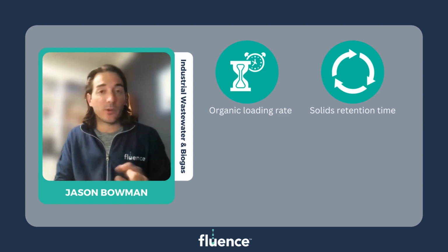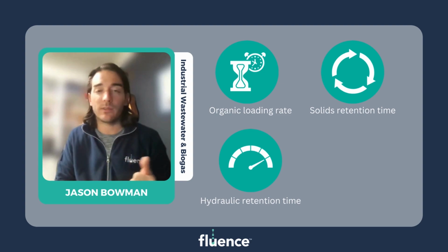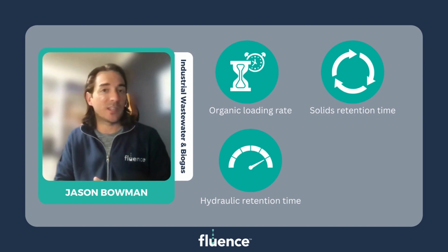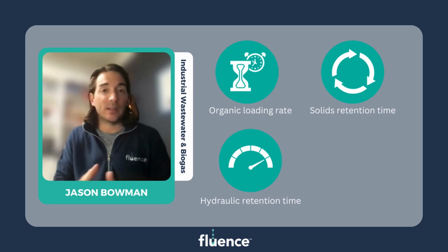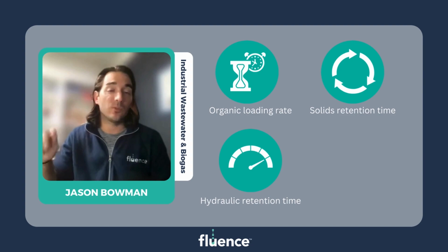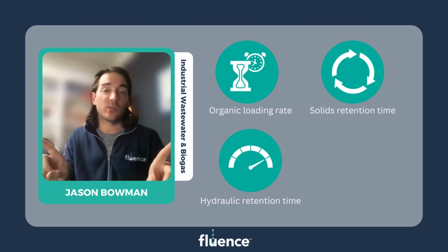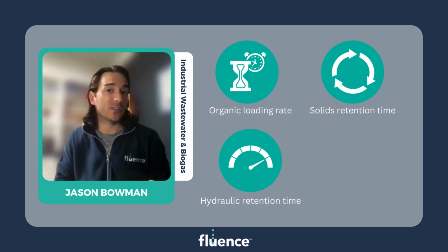So the third design consideration, which I just mentioned, is hydraulic retention time. This is just a high-level overview of how long the solids or liquid slurry is retained within the reactor. When we look at design considerations, the solids retention time and the hydraulic retention time in a lot of situations are kind of one and the same. In other situations, some digesters have a mechanism to collect and recirculate bacteria. In this manner, we can actually decouple the solids retention time from the hydraulic retention time. This is why some digesters are much more high rate than other digesters.